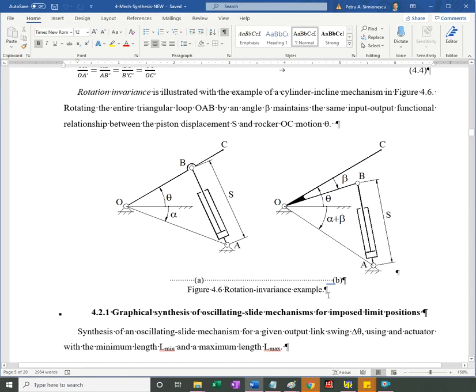And then we have rotation invariance. And actually, it was my experience working with a group of students that figured out a hydraulically actuated arm, but they wanted to have the drive at point C. They wanted to have O, B, and C inline. I said it's better if you can offset B to maintain the strength integrity of it, it was a structural piece of box tubing.